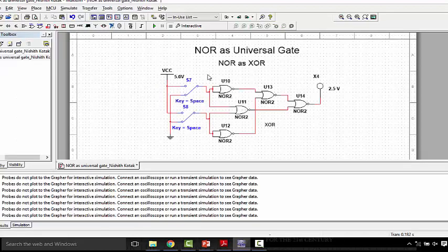This is the circuit corresponding to XOR gate that I would run based on the Boolean expression that we have obtained. I will be running the circuit. Initially, both the switches are connected with ground, that's why I am getting output as logically low state. Since XOR is the inequality detector, whenever I change one of the input states to logically high state, my output would be logically high.